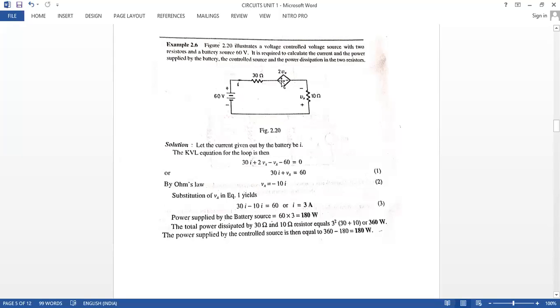Voltage. So now I am telling the definition of dependent source. Dependent sources are represented by diamond shape. Dependent source's value is not constant. It depends on any other element in the circuit. That means Vx they have written. Why have they not written directly 2? Because it is dependent. Okay, what is the dependent value? Vx here they have given. And dependent source values depend on any other element in the circuit.